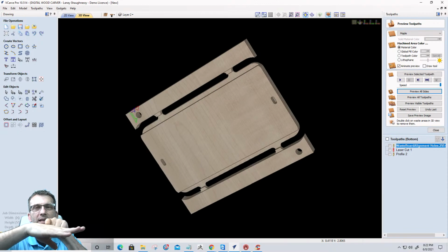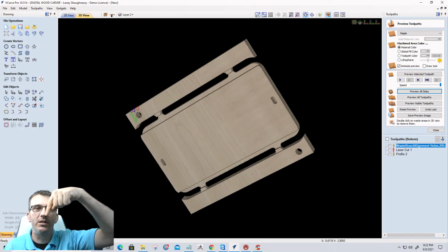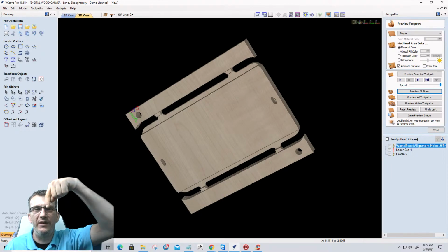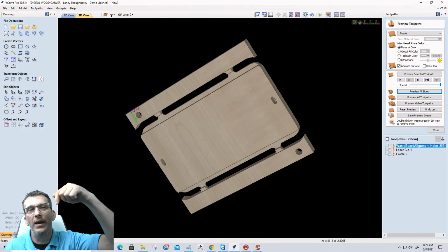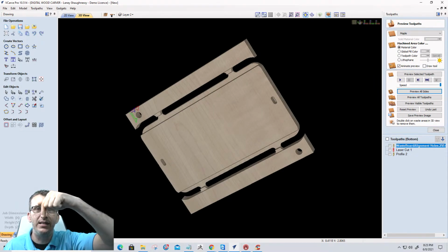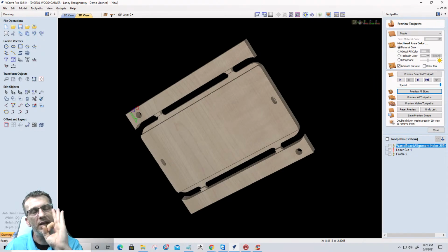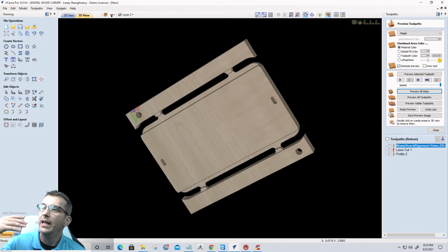But at that point, the top surface has been wallered out. I think that's a word, wallered. That's a possibility if your CNC is not very rigid. Then there's a possibility of wallowing out that hole, especially on that first plunge, and even on the second plunge. But using an undersized bit and pocket cutting will give you a nice precise hole. So that is an option.